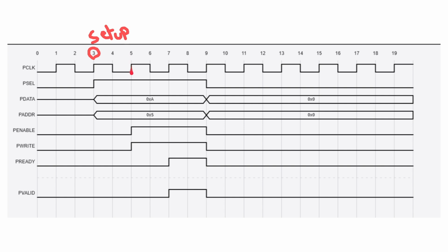So this fifth signal. So in this part, P enable will be high. So telling the system to actually perform the task. So once this P enable is high, it will take the data from the P data, P address, and perform the actual task. So there is P write signal to tell the peripheral to perform the write task. So it will write this P data in this particular address. For example, here 10. So this 10 will be written to the address of 5.